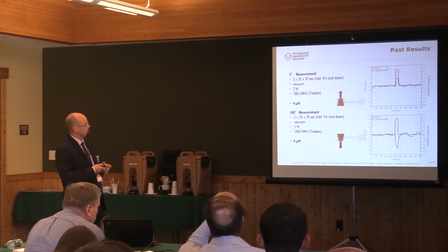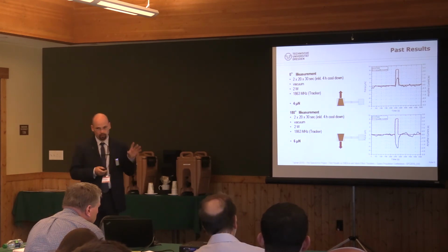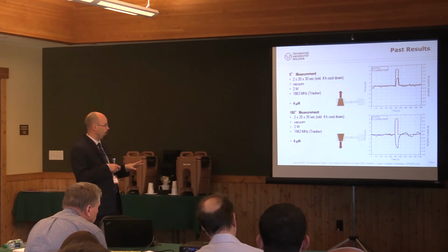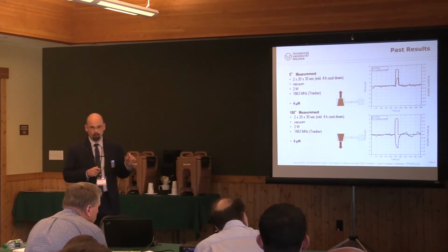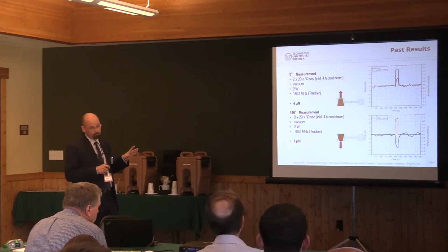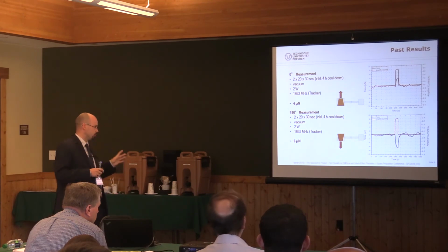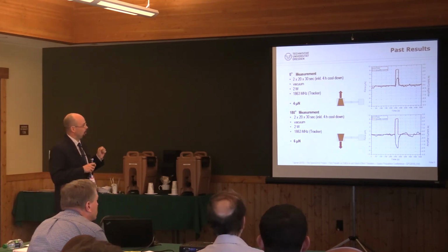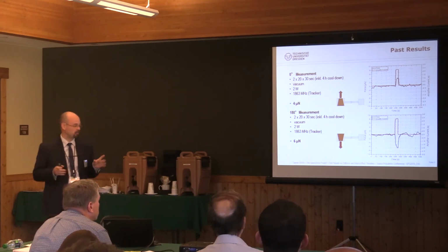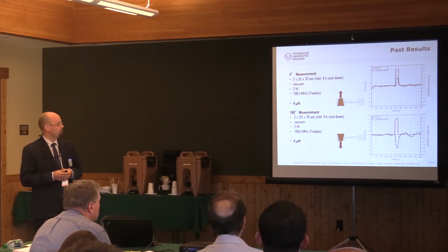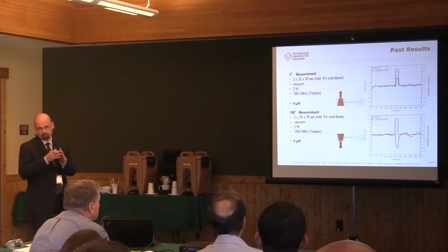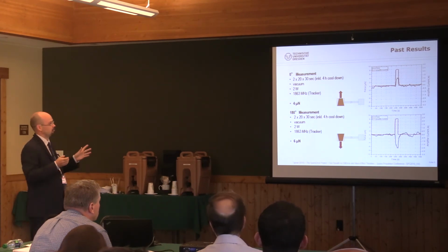We used 2 times 21 seconds each 30 seconds, and because of massive heating we had to cool down 4 hours between those 2 runs. We measured in vacuum, and we could power in with 2 watts on the frequency of 1863 megahertz, and we used the frequency tracker to stay on the frequency even if the cavity expands due to thermal warming or something else.